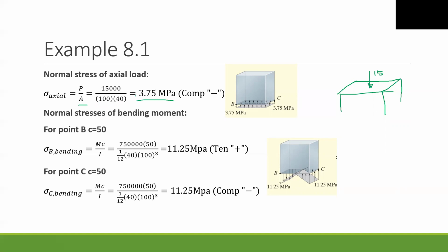You can see I didn't put the positive or negative sign. Then I write the direction using compression or tension. This is the strategy. Sometimes you can follow some formulation using your coordinate system and get positive and negative terms. I don't like to use this strategy because when I work with different axes, especially biaxial moment, the formulation does not work efficiently.